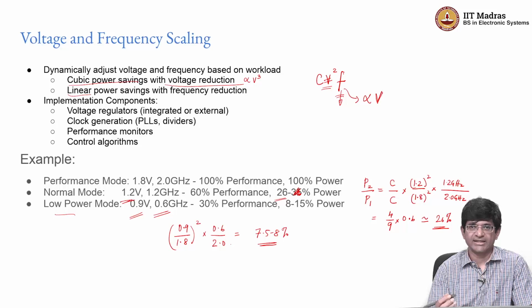So if I, let's say, have 8 CPU cores, it might put them into lower performance mode, where rather than working at 2 gigahertz or 2.4 gigahertz, it's going to bring them down and maybe run them at 400 megahertz, right, and that's the idling speed. 400 megahertz is still a fairly fast speed, but in terms of the power being drawn by the system, it can easily be 1/10 of the peak power that would otherwise be drawn if it was operating at full speed, right. So voltage and frequency scaling is a very powerful tool and pretty much required in order to get good performance out of modern systems.